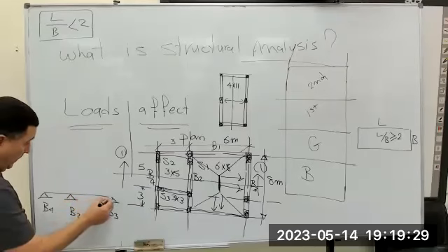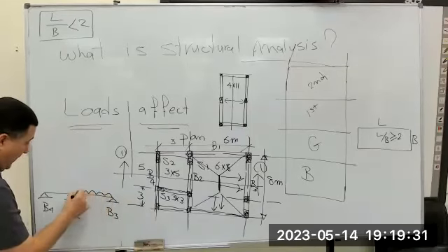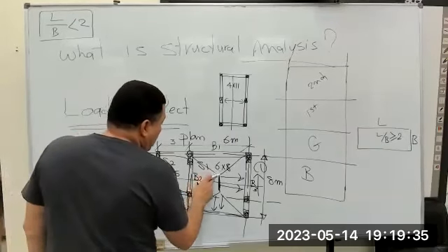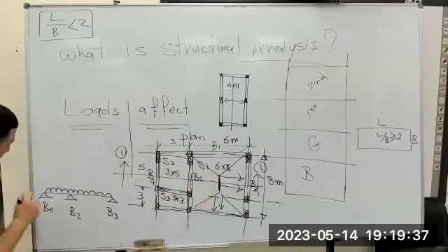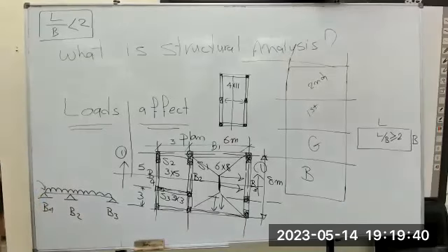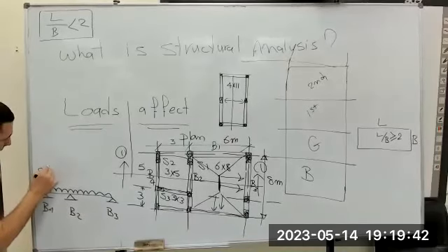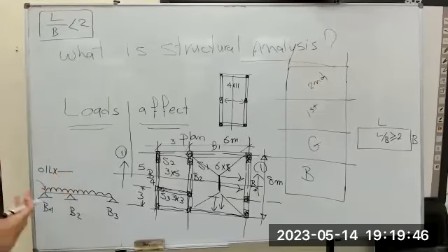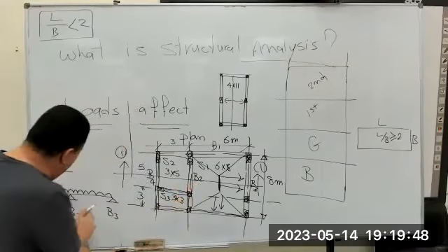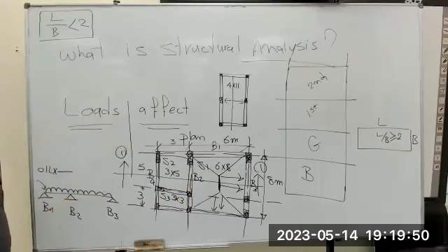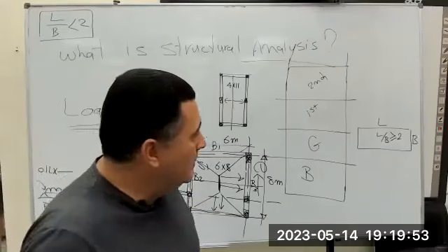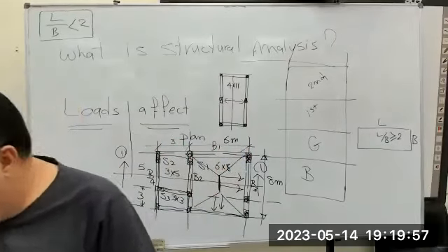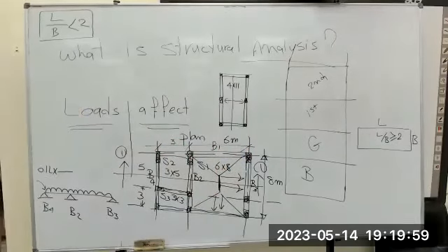Slab. So now the load we can take it as a uniform load. We take a coefficient and then we distribute it into a uniform load, something like 0.1 L multiplied by our coefficient, I don't remember, but in the end we will take all the slabs' distribution into the beams. Okay. So loads: live load, dead loads, and wind load.